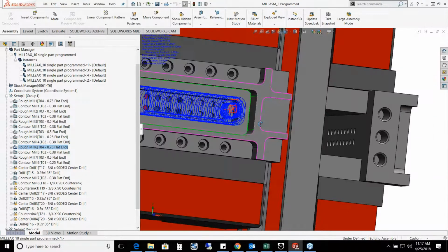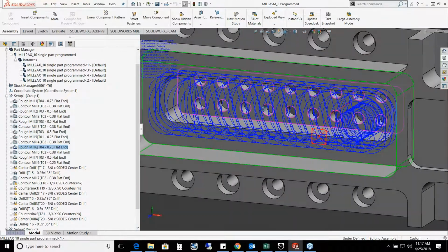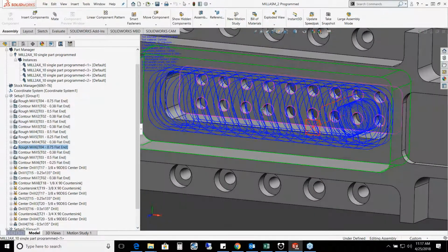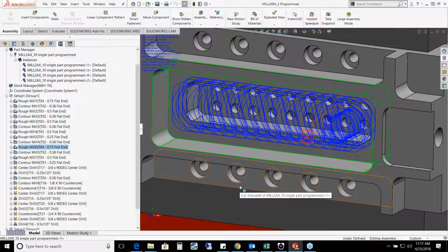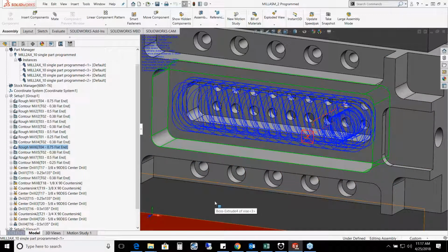The toolpath in Volumill is unlike any other. Hopefully everyone can see that really well. It is an algorithm developed via a technology called chip thinning. The idea is that the tool can take a much larger depth of cut and be able to run literally four times faster.